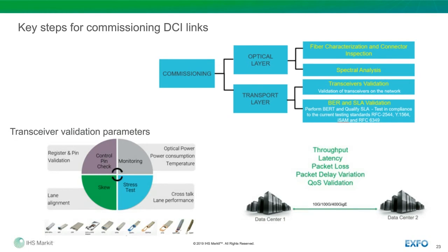Inside the data center, as links are shorter, typically the data center operators will only test the transceiver. They won't do a performance test of the links. All the transceivers, as well as the DAC cables and the AOC cables, need to be qualified to make sure they work properly. So that's really from an operational view.